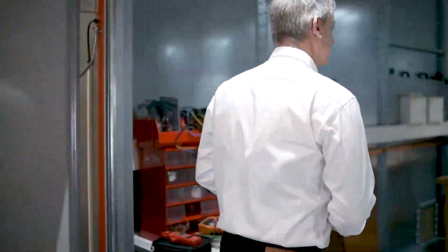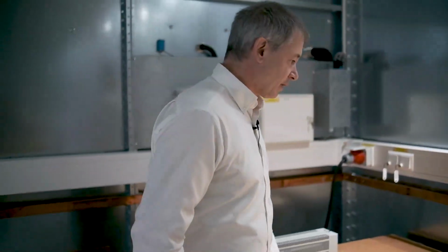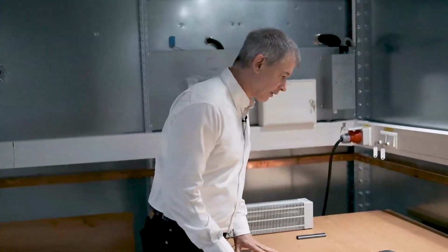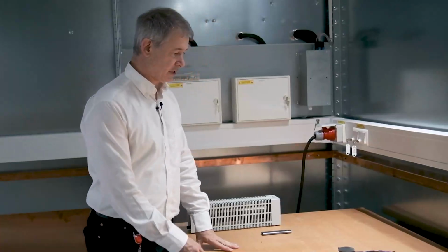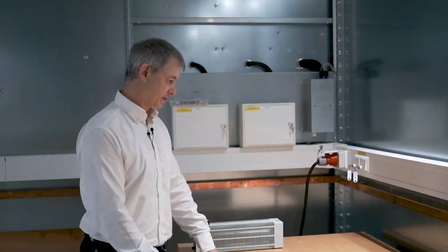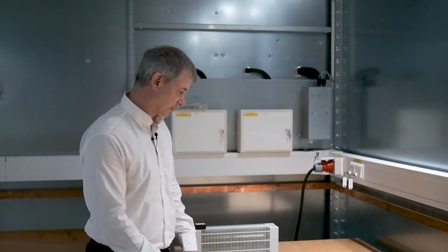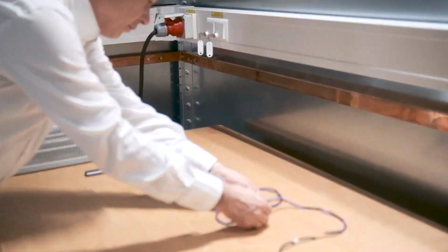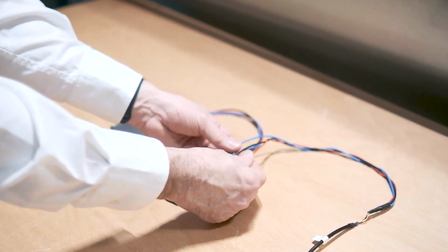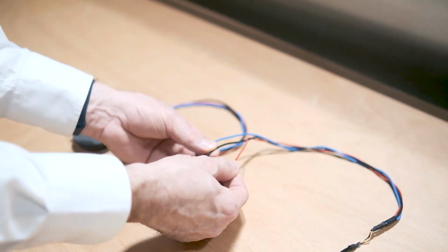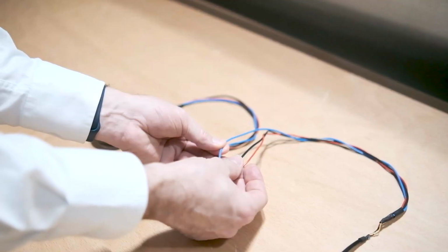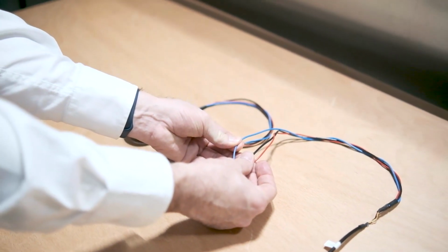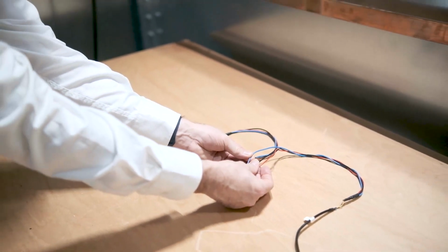Let us go back to the chamber. If I look at the graphs, I can see a harmonic at 360 kilohertz. That means I expect differential mode noise on one or on all three lines. We have the ground line, the VCC line, and also a control line from the USB side to get the high power system.